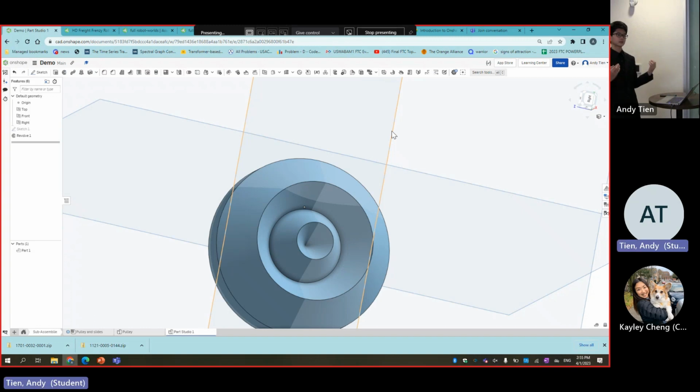So this software is called a slicer. What it does is it reads in your file, and the slicer itself has another software to decode that and turn that into paths for the 3D printer to follow, and that creates a G code file. And then what you do is you save the G code file onto an SD card, and then you insert it into the printer, and the printer will read the G code file from the chip, and it will tell your printer in what ways to move the nozzle in order to create the part you want. Do we have any more questions?